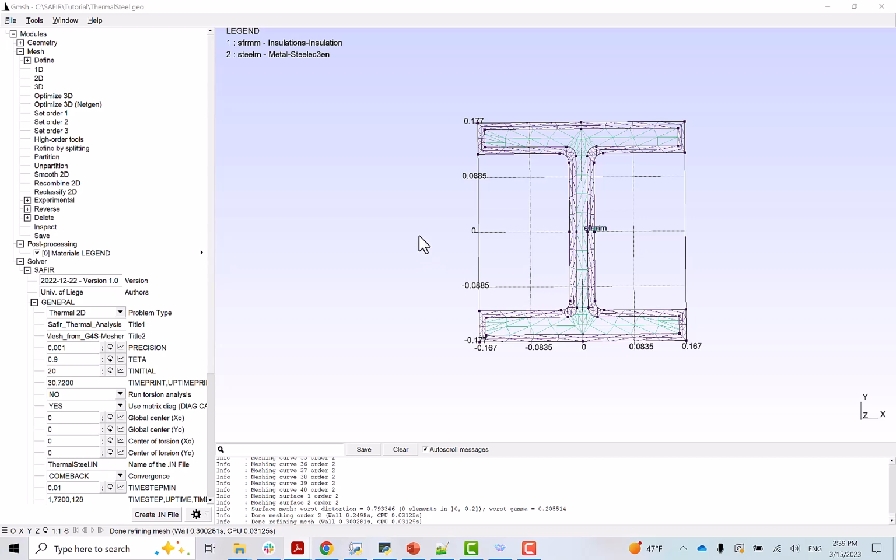So if you use a very fine mesh and the model does not run, make sure to check in the output file whether there is an error message specifying that it's because the number of nodes or elements exceeded the limitation of the demonstration version. The model is now completed.